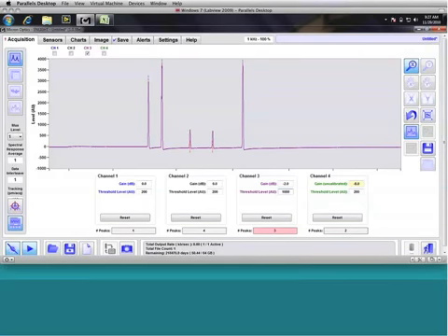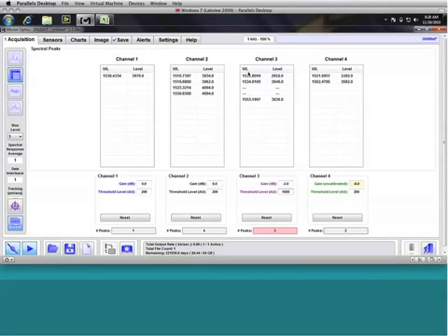As Dan explained a minute ago, all of the internal distance compensation and averaging, all of those processes, are done inside the interrogator, so it's very important that the application remains synchronized. Now if we go over and look at the table, we note that even though only 3 peaks are detected, both ENLIGHT and the SM130 are aware that there were 2 additional peaks we're expecting to receive, so that the remainder of our data processing chain will continue undisrupted, and there won't be a wholesale shift of this 1553 peak down to the position of peak sensor 3. And that'll be very important as we establish our sensors in the next tab.